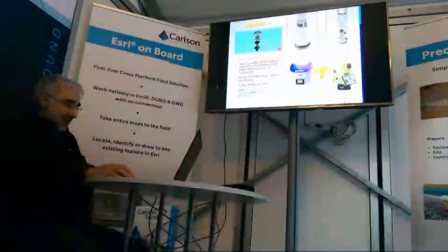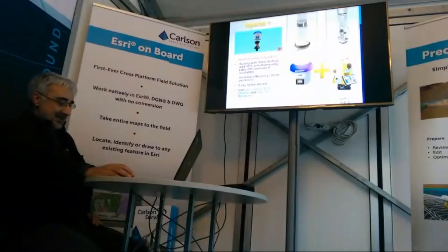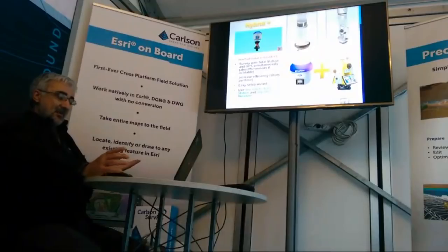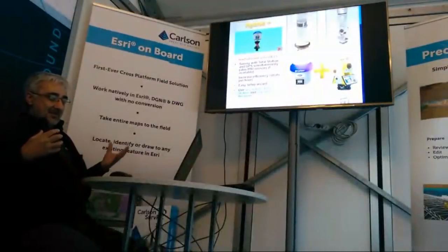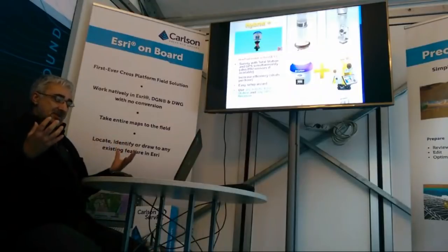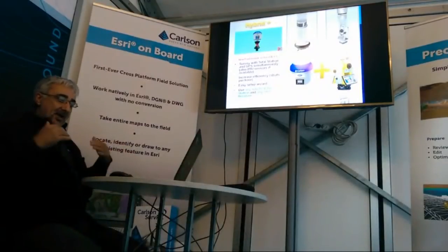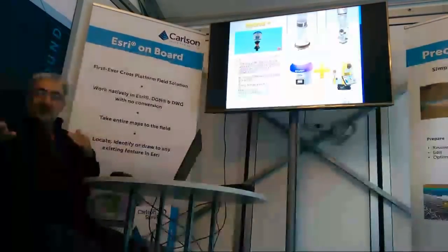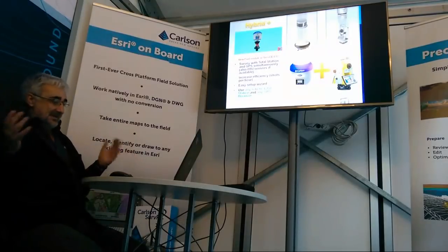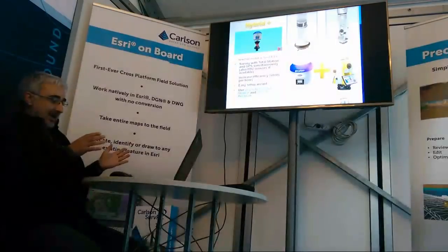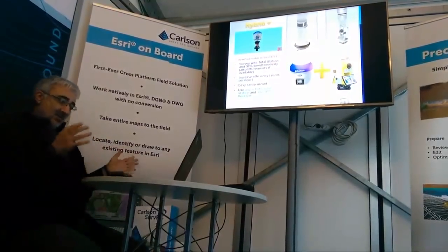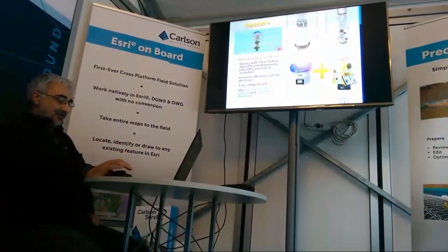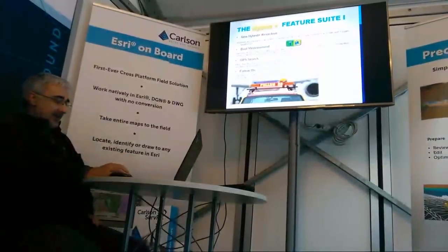We also added one of the things to highlight, an easy setup by the wizard, a very easy wizard, because it is better to help on not making mistakes when you're combining GPS and total station to synchronize, to align the two measurements. GPS works on the grid, total station works on the ground, different scales, how to do it. So it's easy, and you get very good guidance by using this wizard if you want to. Otherwise you can configure everything manually, but it's better. And more features we have related to hybrid.